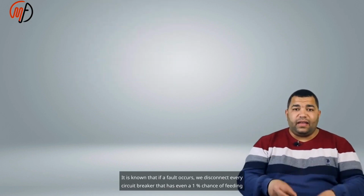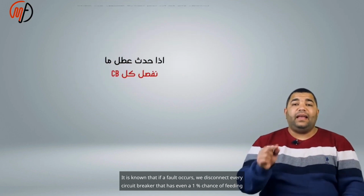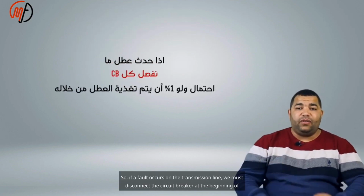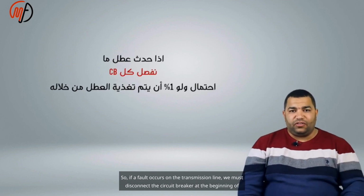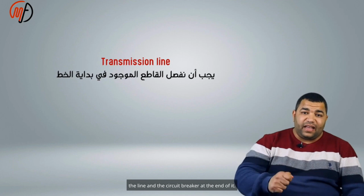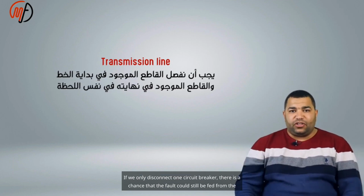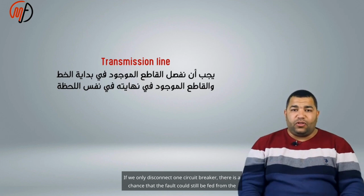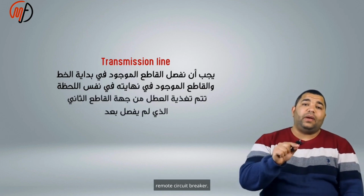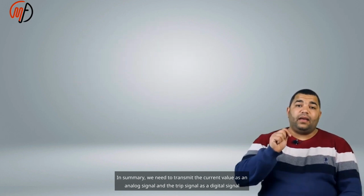It is known that if a fault occurs, we disconnect every circuit breaker that has even a 1% chance of feeding the fault. So, if a fault occurs on the transmission line, we must disconnect the circuit breaker at the beginning of the line and the circuit breaker at the end of it. If we only disconnect one circuit breaker, there is a chance that the fault could still be fed from the remote circuit breaker. In summary, we need to transmit the current value as an analog signal and the trip signal as a digital signal.